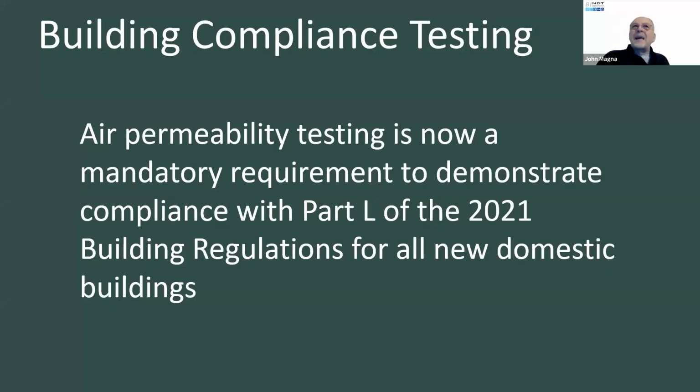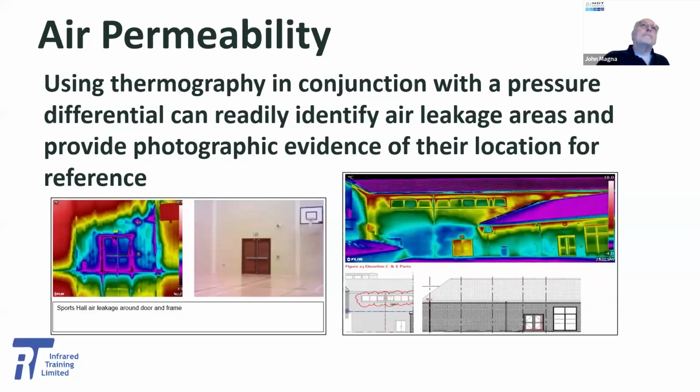Building compliance testing, air permeability tests are now a mandatory requirement to demonstrate compliance with part of building regulations for all new domestic buildings and new commercial buildings over 500 square meters, including extensions with a floor area greater than 25% of the current building.